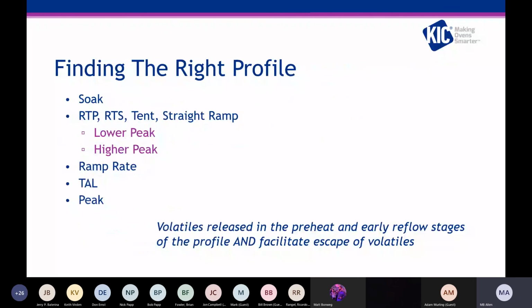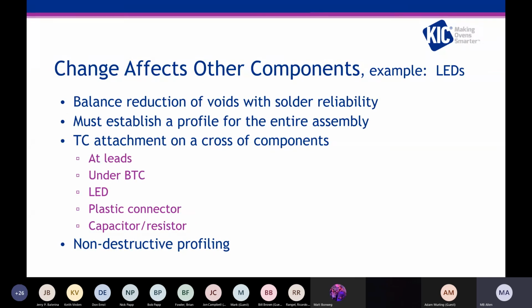The ramp rate is also an area of the profile to focus on, but the time over liquidus is very important as well. And of course, your peak temperatures. With the lead-free materials, we do see high peak temperatures, and in some cases, the recommendation is to go even higher. And so then you have to take into consideration some of your more sensitive components.